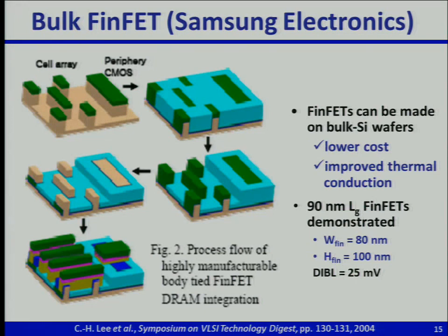So basically what you need is some heavy doping. Like for an N-channel device, you'd make that heavily P-type at the base of the fin to prevent leakage between the source and drain that's out of control of the gate. So you need some retrograde doping at the base of the fin if you use bulk silicon as the starting substrate. That retrograde doping step is not trivial, to get very steep, suddenly increasing doping beneath the gate. So you need that.